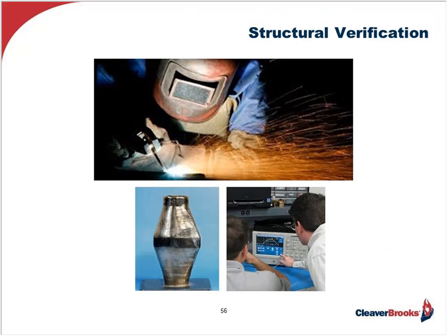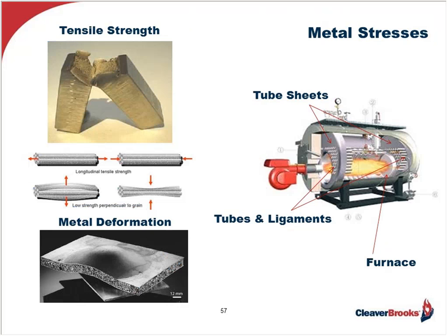The process also includes a thorough analysis of the structural implications when one is applying the amount of heat transferred in the boiler, along with the dramatic swings in delta T's involving varying circulation rates, I should say, and associated heat fluxes. For instance, analyzing the furnace and its stresses, because it's the area receiving the greatest amount of heat and the huge delta T's that I spoke about. What should the thickness of the furnace plate be? And should it be corrugated to lessen the cost or average mean temperature of the steel relative to its thermal expansion limits, yet providing sufficient strength in all the weld attachments?